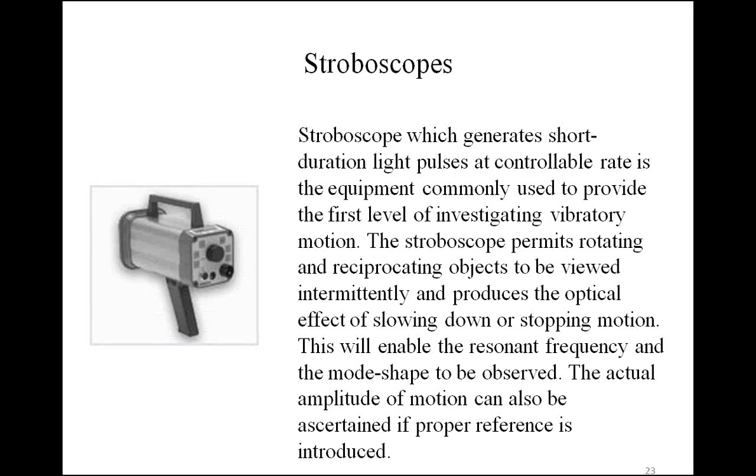In sinusoidal testing, the advantage is that you're at one frequency, and many people want to look for these resonances. And what's really nice about sinusoidal testing is that now you can synchronize the stroboscope to the test, and you can look at these resonances in slow motion, or fixed displacement, and it makes it much easier to first understand what the resonance looks like, and then also to perform some kind of adjustments on your products to improve them, and then verify them by going back into dwell.